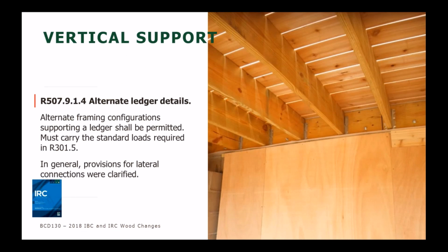There's a section that says alternate ledger details. The intent here is to say that we have called out within the IRC one type of ledger connection, but you can do whatever alternate you want, and this just clarifies that the alternates are fine. As long as they're equivalent in strength, they're good to go.